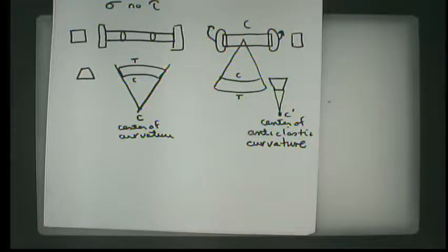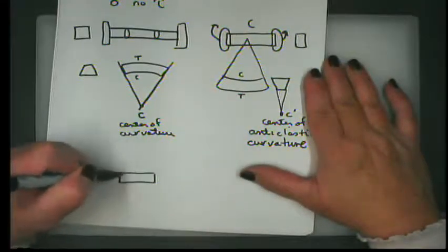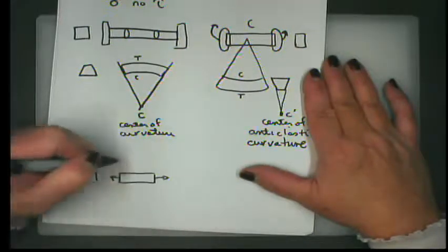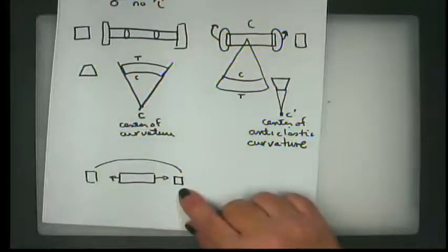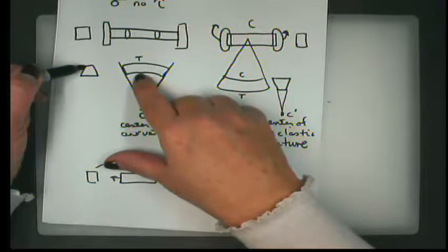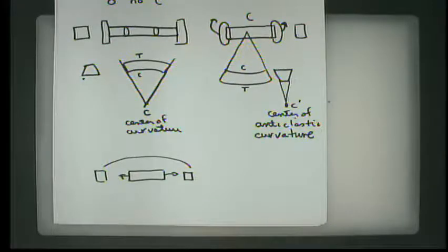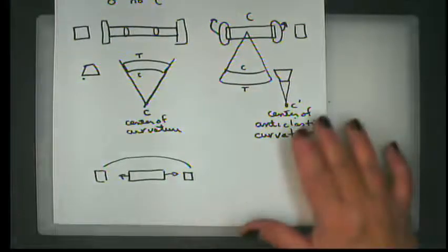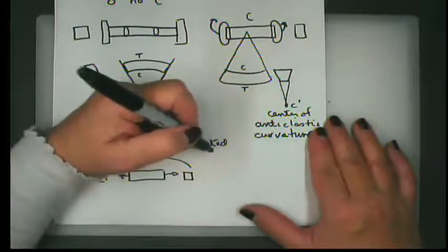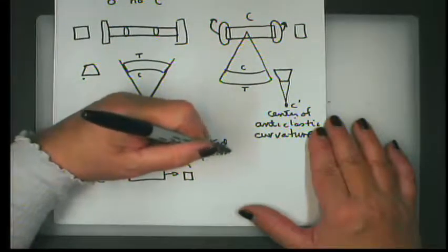So if you think about Poisson's ratio, think about just stretching a prismatic member, okay? If it elongates on this axis, it's going to contract on the other axis, isn't it? Okay? If it's a homogeneous material. So it's the same thing here. If it expands here, it contracts on the axis. If it contracts here, it expands on the axis. And we're talking about homogeneous materials, but it's related by Poisson's ratio here, just as it was with an axial load on a prismatic member. Good question.